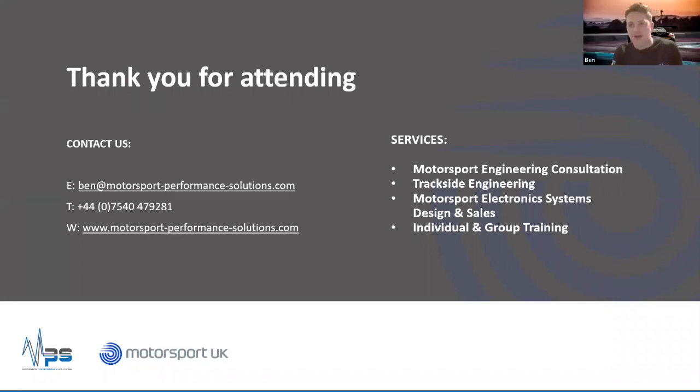That's a more complex question in its own right, and it's probably beyond the scope of this presentation. Again, I would say this presentation is concentrated on driver performance. And using the 80-20 rule I discussed, as long as your acceleration sensors aren't moving in the car, so they're at a fixed position, for driver performance you generally just really want to know the trends.